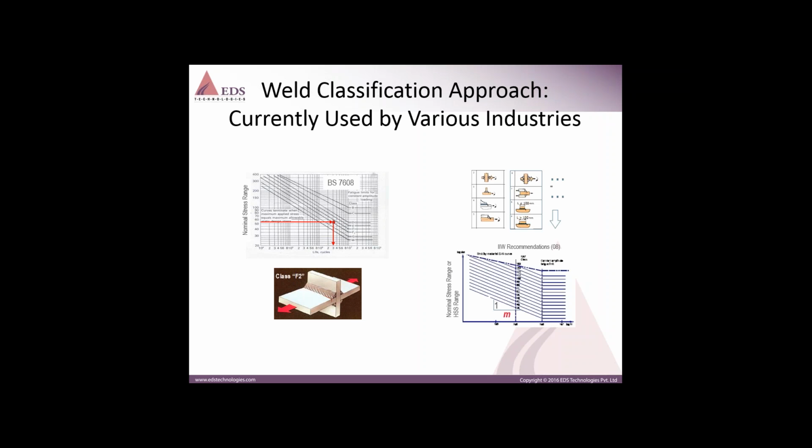Then you can go into this diagram with the nominal stress range or even hotspot stress range and work out what your fatigue life is. British Standard 7608 is included with the basic license of your fe-safe and uses normal stress in a critical plane searching manner.